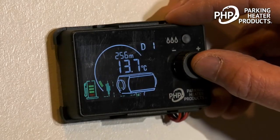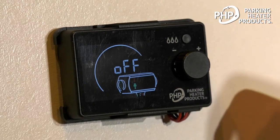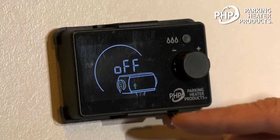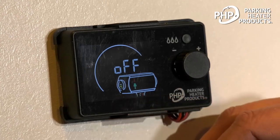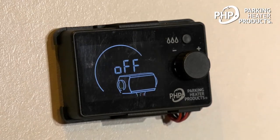Heater shutdown. When the heater is switched off, either manually or automatically, it requires a cool down period. The fuel pump will continue to pulse for a short period and then stop pulsing. The flame will slowly be extinguished. The glow pin comes on for a short afterglow period to clean off any unburnt fuel residue. And the blower continues to run for a 3-minute cool down and then switches off.